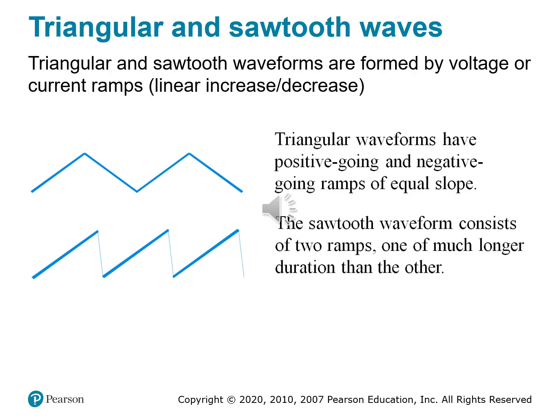The sawtooth waves are heavily used in sweep generators, analog TVs, and CRTs, and phase lock loop systems, because they change steadily in one direction and reset quickly. They're great for frequency control and scanning systems.